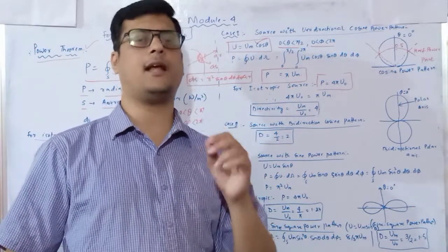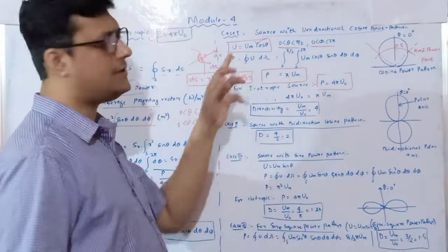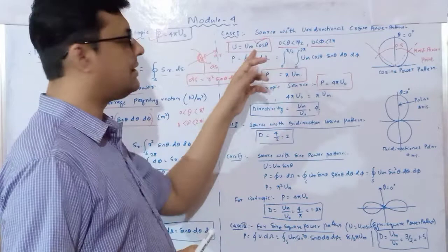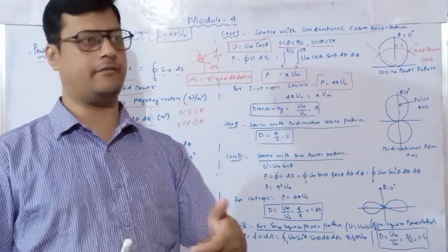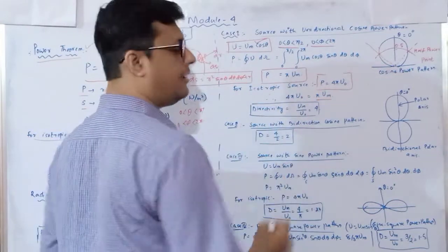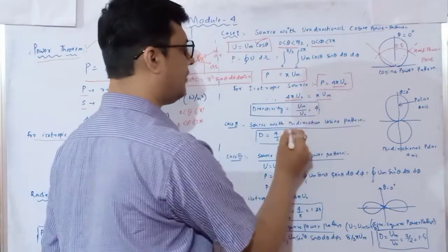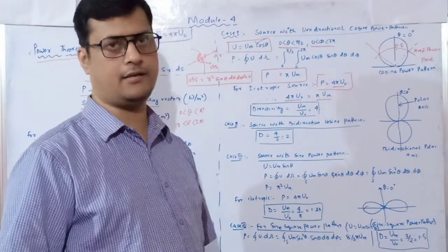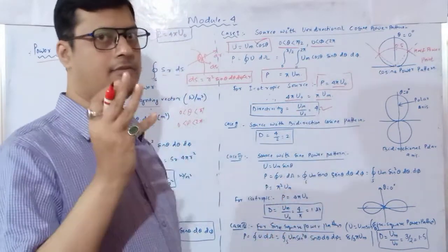At theta equals 0 degree, we have the u naught value. And um is the maximum value present in our intensity. So if you take the ratio of maximum by the reference value, you will get the directivity. So here the power is pi into um and the isotropic power is 4 pi into u naught. If you divide this by u naught, you will get your directivity. Okay. So directivity is equal to pi um by 4 pi u naught, that is 4.